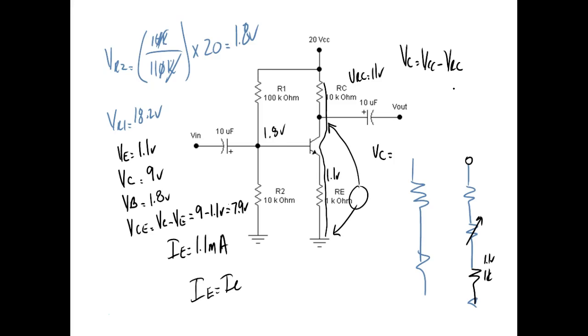We said the voltage drop of VRC is 11 volts. If it drops 11 volts and I have 20 volts there, then that leaves 9 volts sitting right here, right? You understand? Now, notice the sum of this and this equals 9 volts because we're looking across both the emitter resistor and the collector. So now we're ready to roll, guys.